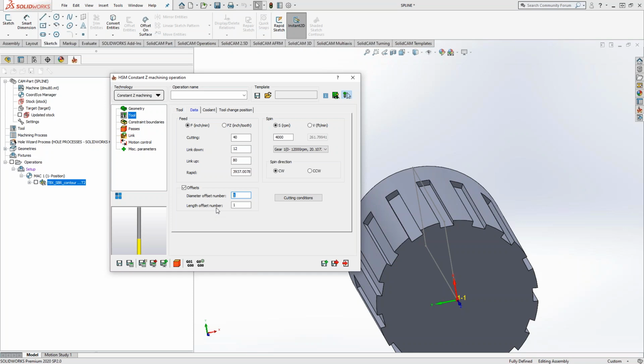So my recommendation would be to do this. So then in this one operation, if you're looking to have the ability to add some sort of modification to the diameter, rather than going and changing the diameter for use of the first tool throughout the G code, for this one operation, you can change it to, let's say, D11, and then on the machine, define a D11 or a D21, 31, whatever you want to call it, and then you can actually add in a different diameter for the same tool in your turret or in your carousel, whatever you want to call it. So that gives you the ability to kind of modify on the machine side. It's not fully cutter comp, diameter comp, or anything like that.